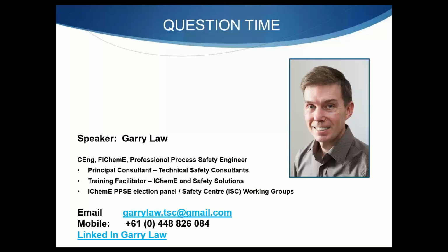Okay, thank you. Any possibility that a missing vortex breaker at the bottom of a vessel disturbed the reading of the level measurement? Any incident experience related to this case? Yes, I've had vortex breakers where the flap of metal that goes across has broken away, and so you do actually get the vortex, and that does cause level measurements to fail. Particularly if you've got something like radar pointing to the wrong place within the vessel, then you can have lower levels and different readings because of the vortex. It can also vortex towards the side of the vessel, and then you're reading a level from a bridle that's nearby, and it will give you the wrong result. So yeah, I've seen that.